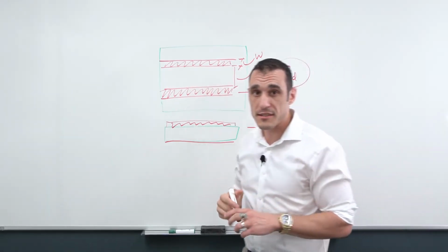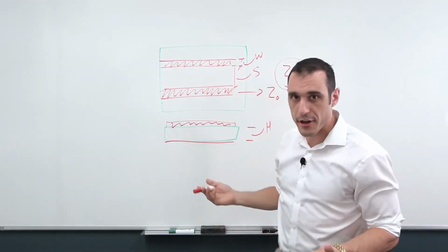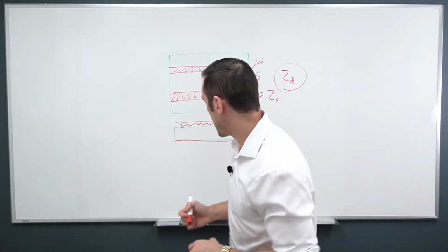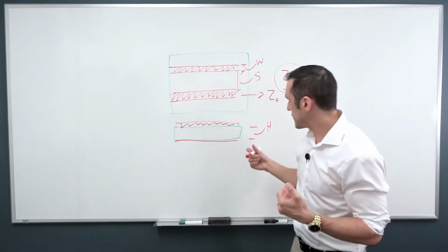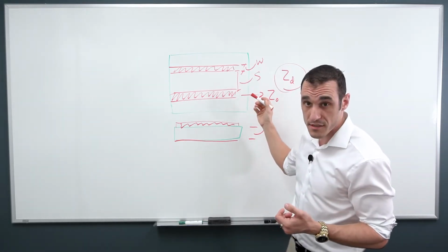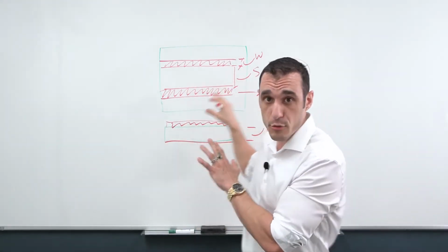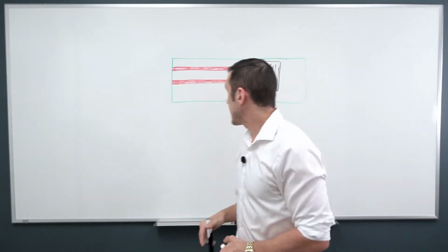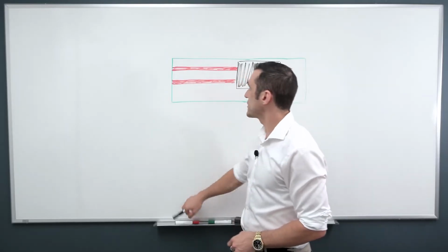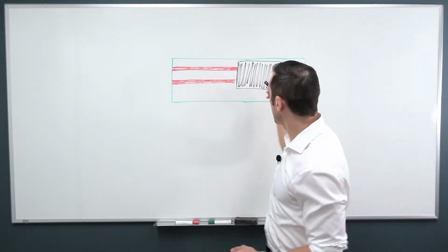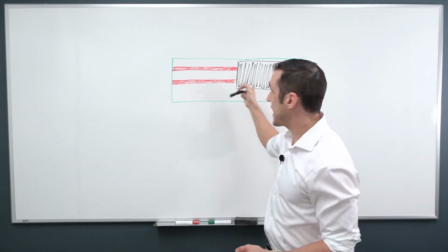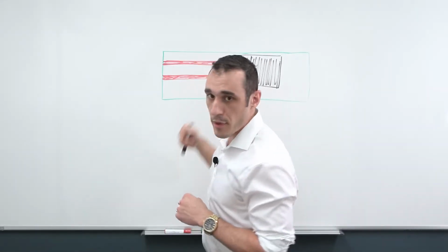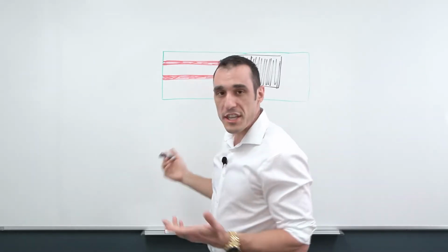So now the question is, how do these two traces carry a signal? This is, I think, something that can get a bit confusing, but it actually relates to the same idea that's used to measure a signal just between one of the traces. So I'm going to redraw some of this and we'll look at how exactly the signal gets read out by a receiving component. So now what we want to look at is how exactly does this pair of traces carry a signal, and then how is that signal actually read out by the component that connects these two traces? So if you look at the signal that's carried by a differential pair, the signals are equal and opposite.